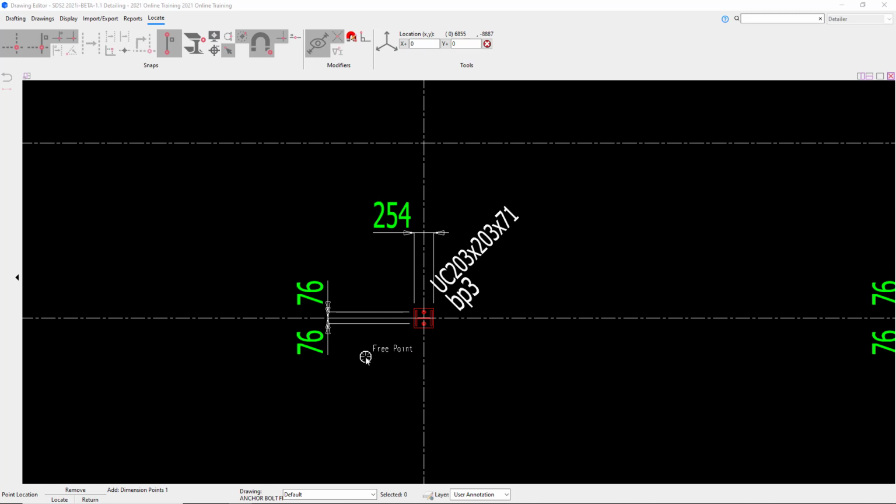So we can see, since I'm still in the dimension add tool, if I hit my shift button, it gives us the actual dimension for left click, our drag off dimension for middle click. If I hit control, our left click turns into an arc dimension, our middle click gives us an angle dimension, and if I would hit shift and control at the same time, our left click would turn into an actual dimension, our middle click would be a vertical dimension, and our right click would be a horizontal dimension.